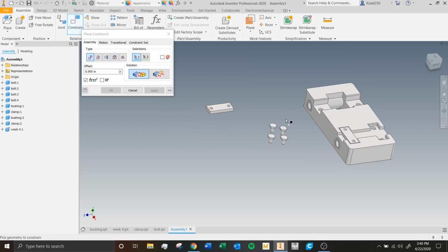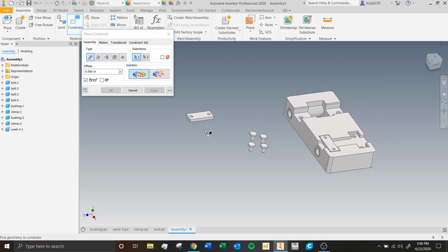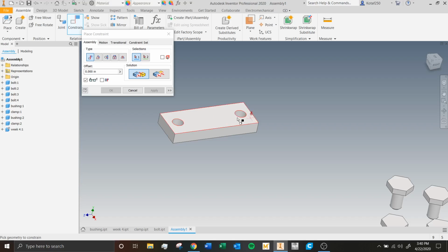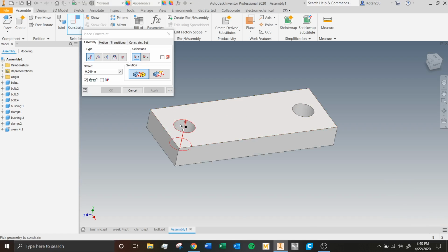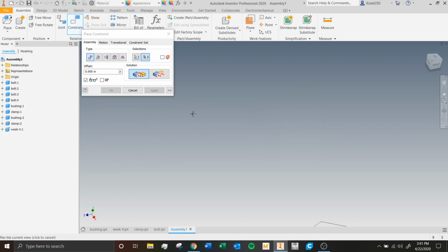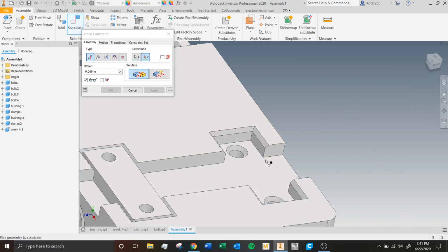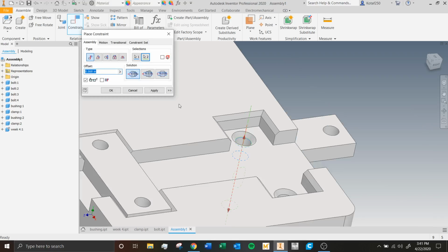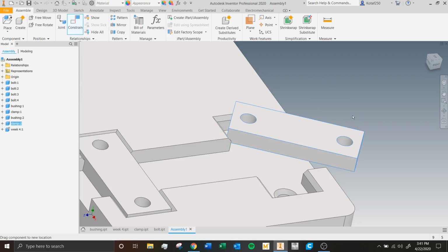Now there are different ways of doing it. You didn't have to do it in that exact order, but I'll show you why I personally like the holes. They're a lot easier to use. So what we're going to do is select this hole, go over to our part, and I want it to mate with this hole. So now these two holes have the same axes. If we move it around, it just spins around.